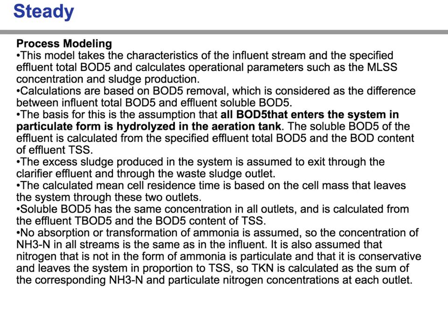So we have the input conditions and the target conditions, and process design means that this program can choose the operational parameters to satisfy these conditions. So the MLSS or sludge production can be calculated.